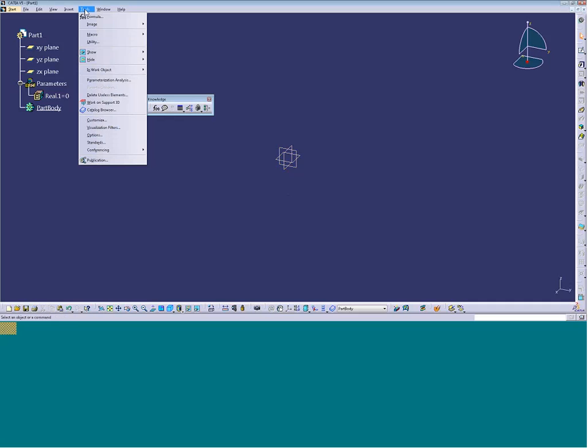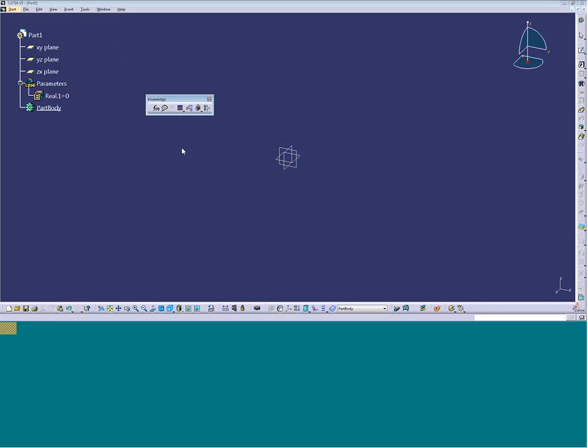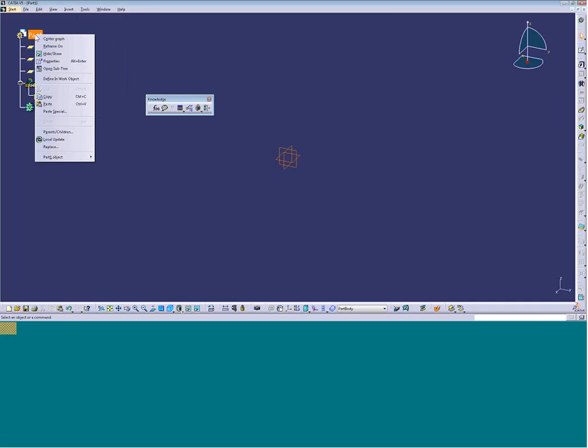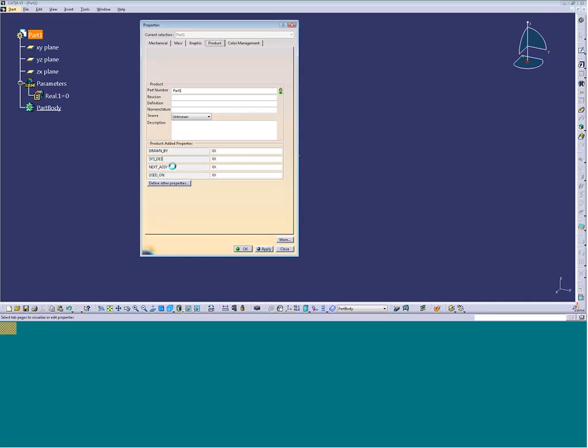And so we wrote a little macro to go do that, and I'll go ahead and run that. That was the one for populating 3D parameters. If I just run that, it comes in and tells the designer that 4 of the necessary parameters were added to the product properties. And if we come back in and take a look at the properties at this point, you can see that what they were looking for was drawn by, system designator, next assembly, and what it's used on. And now all they need to do is come in and edit that data.